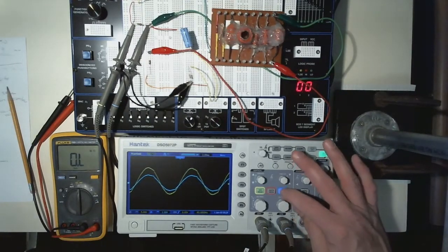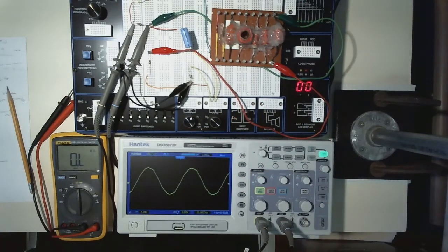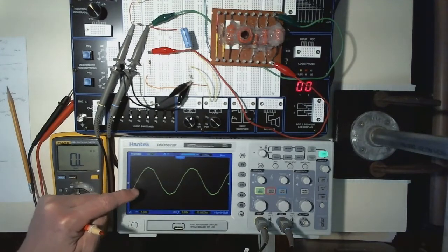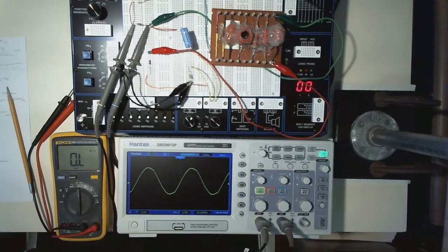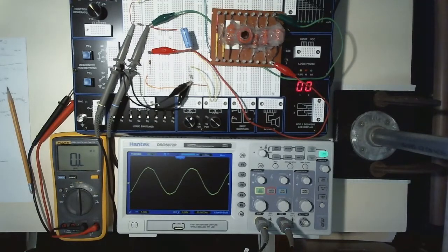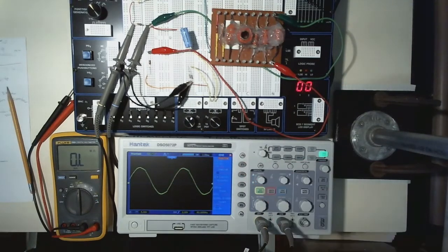The other thing is, let me turn off this channel 2. So if I'm looking just at channel 1, and this is where I was saying that I'm using a little different source and I've got a little more voltage there than I was talking about, it looks like I am at about 2 divisions at 5 volts per division, so I'm going to be, what, 10 volts for my amplitude, so about 20 volts, close to 20 volts peak to peak. It looks like it's not perfectly centered, but that's okay. That could be in the source. That's not going to change where they cross necessarily. If I want to double check that, I could go to this thing. I could look at grounding that.